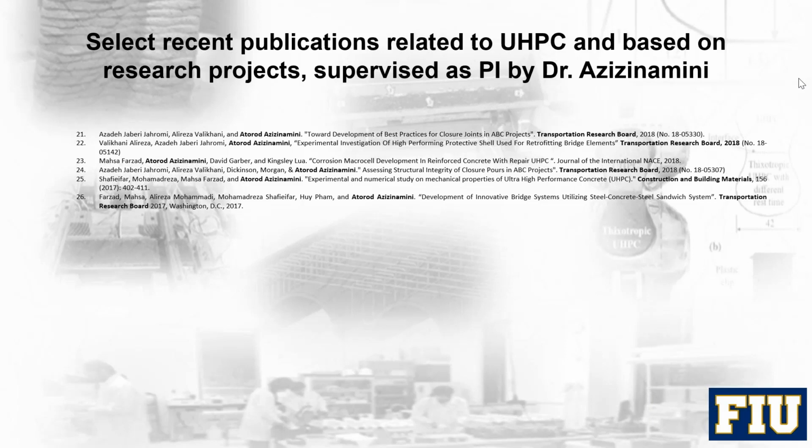These were using exactly the same fibers that we've used in the non-proprietary UHPC, with very high tensile strength and everything. The trick, in our case, was that we had to prime the line using a mortar. So we would place just a regular mortar that flows very easily in the pump, and then the UHPC right behind that. Once the pipe was filled, the flow would start to go, and the static friction and all that is gone.